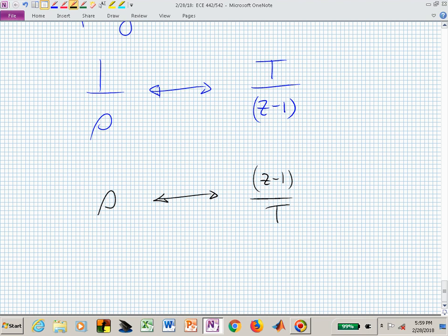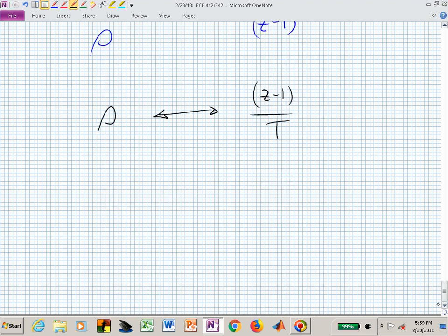We've now cooked this up, and now it's coming out of the oven, and we've figured out what to do with this forward numerical integration approach. We can now say anytime you give me a transfer function, C of s, and you want the C of z, everywhere I have an s, I just replace it with z minus 1 over T.